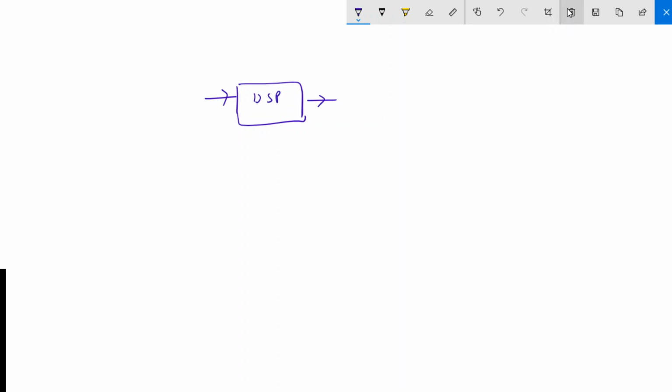Now we have a digital signal at the input, you have a digital signal at the output, and before this we have done A to D conversion that I have not denoted here. So one error you get here because of this A to D conversion, that is quantization error. So x(t) was converted into x(n), analog to digital, and because of the finite word length of the processor you have some quantization errors here.